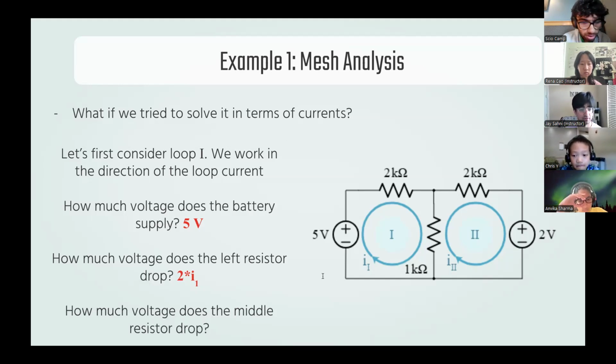And just a quick note, you'll notice this circuit has resistances in kΩ, that's kilo ohms, that's thousands of ohms. But I'm just going to write it as if it's a regular number. And then all that's going to change is that the final currents that we solve are going to be in milliamps, as in 1,000ths of an amp. That's on a lot of circuit lab tests that you do in SciOly Virtual in particular, they like to do things in terms of kilo ohms because that's more physically realistic.